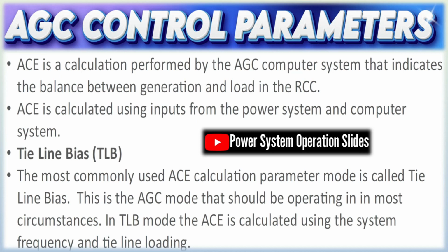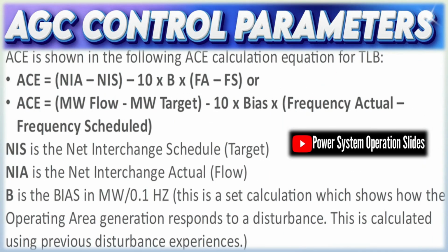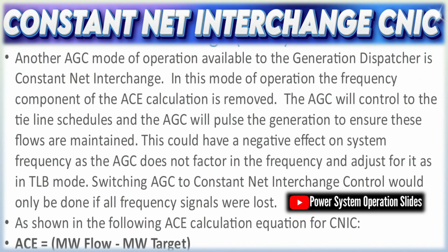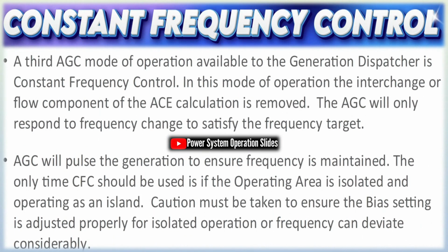AGC operating functions. The main functions integrated into AGC include monitoring, tracking the frequency, generator output, and tie line flows. Error calculation, using measured data to compute ACE. Control signal dispatch, sending commands typically through SCADA and digital control loops to generator governors. Feedback and tuning, continuously adjusting the gain and participation factors using methods such as proportional integral control so that the control response is both prompt and smooth, minimizing overshoot or oscillations. These functions ensure that both fast transient disturbances and longer-term load changes are managed effectively.